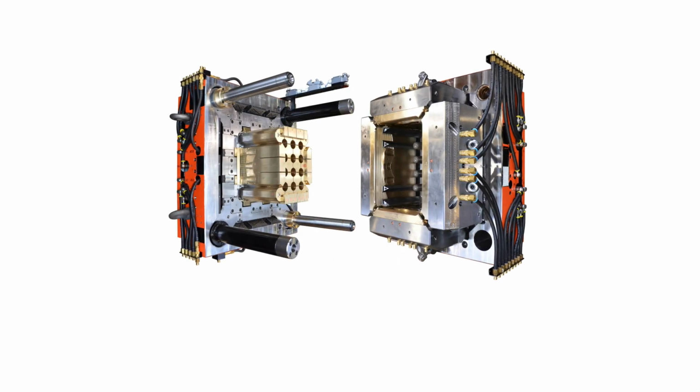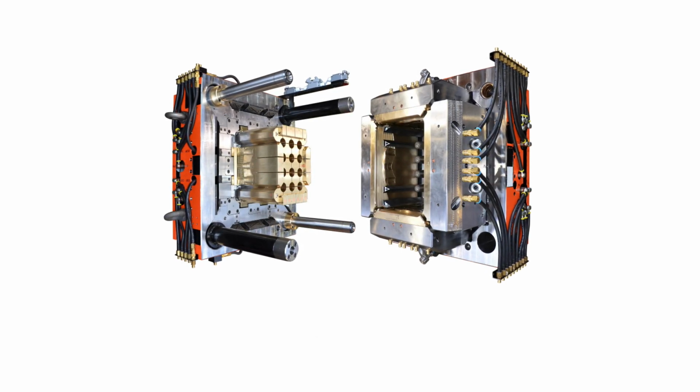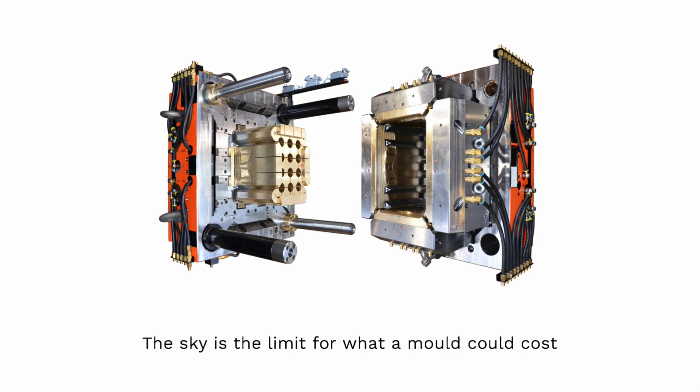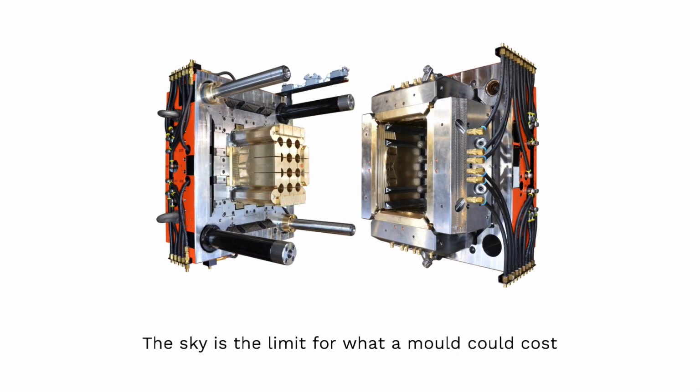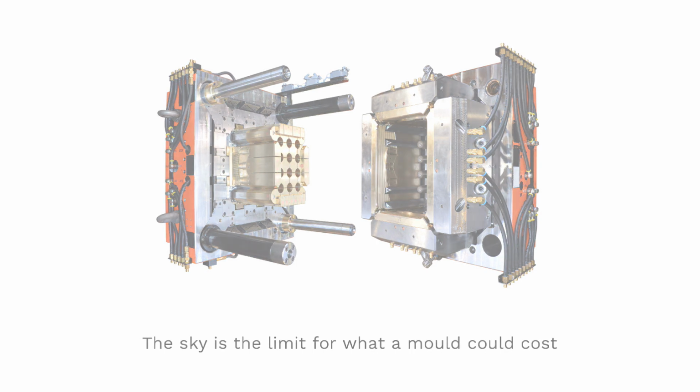And then if we get to really large and very complicated parts with a lot of moving mold pieces and a lot of complex geometry, then the mold cost can easily reach 100,000 and beyond that. So those types of parts we should probably avoid unless we have a huge budget that we are willing to spend. And now to wrap up with injection molding, let's list a couple of key takeaways here.